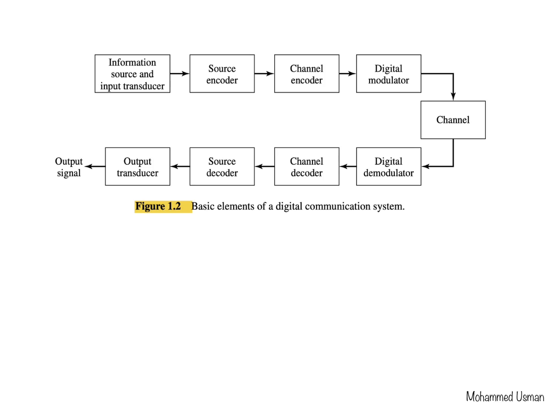Quantitatively, of course, there would be some difference. Again, that depends on the type of compression. There are two types of compression called lossy compression and lossless compression. In lossy compression, of course, there's going to be some degradation in quality, but as long as the end user is not able to perceive that degradation to a significant effect, then we are okay with that.